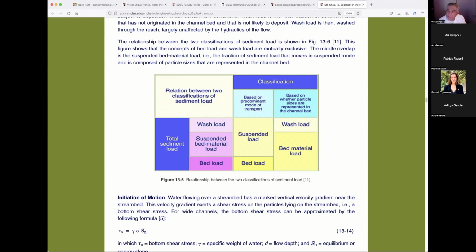And if you go further down to the estuary, where the velocity of the flow starts decreasing because of the proximity to the ocean, then we can have some silty beds, or beds that have some silt in them. But it's not typical. Most of the work that has been done in sediment transport by hydraulic engineers is in sand bed channels, in the middle, in the valleys.